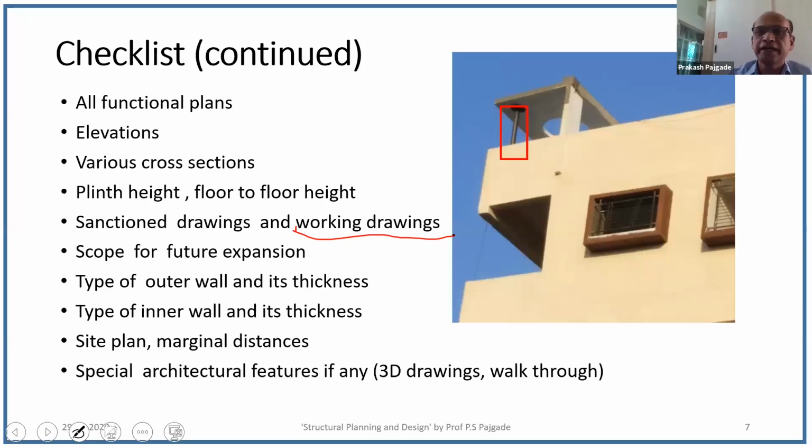Now, this is one of the buildings where initially the architectural elevation was not developed. Later on, some features were added, and the contractor himself constructed this small architectural feature. You can observe here, the cantilever slab is quite large, and it's not stable. So they have to provide temporary support for stability.